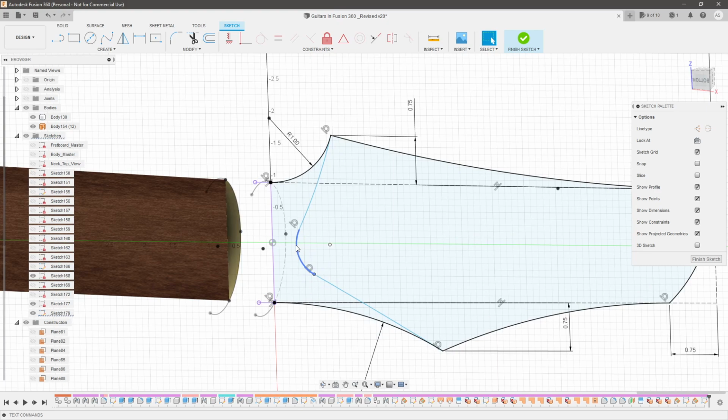So now what we need to do is make this touch the nut line. Now that's where a lot of people got hung up when they tried to do this on an asymmetrical design, because on a symmetrical design you can just make this a midpoint to here, and that makes these two endpoints vertical to each other. Now on an asymmetrical design, that's really not the case, and that's actually not what we care about. What we care about, so the design intent is that we care that this arc is tangent to the nut, and that the peak, the furthest point on the top of the arc, is touching that center line. That's really what we care about.